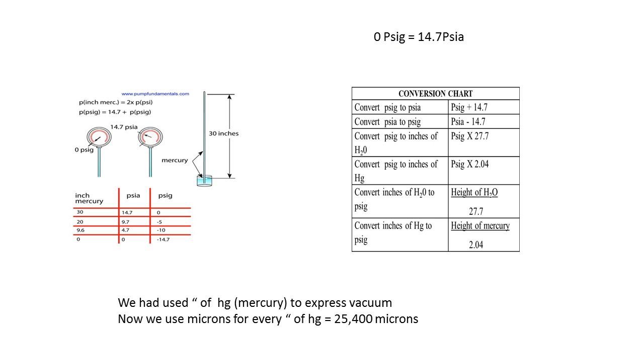When servicing refrigeration systems, we use gauges to check what the system pressures are. Our gauges read pounds per square inch gauge, or PSIG. This measurement does not include the pressure of the atmosphere, which is 14.7 pounds per square inch at sea level. Pounds per square inch absolute, or PSIA, includes the pressure of the atmosphere. So 14.7 PSIA equals 0 PSIG. Most HVAC equipment pressures are measured using PSIG, but some equipment does use PSIA, so it's important you understand the difference.